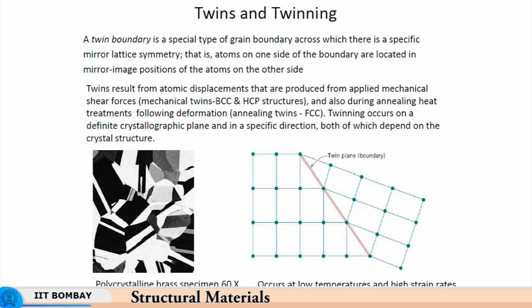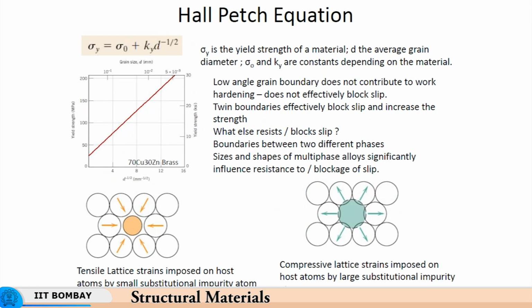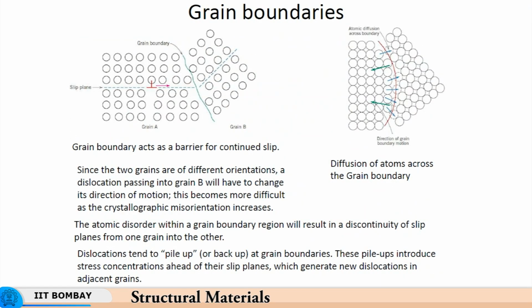There is another mechanism of deformation, and it is other than slip. What we were talking about is slip, essentially a dislocation moving along a slip plane, the shear plane along which the dislocation moves. So, one crystal slips with respect to another.